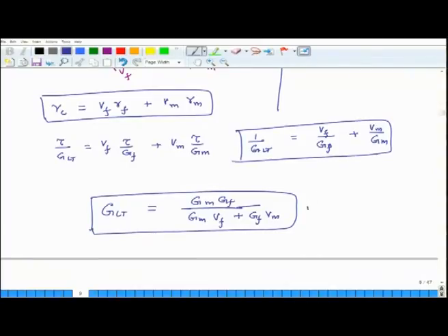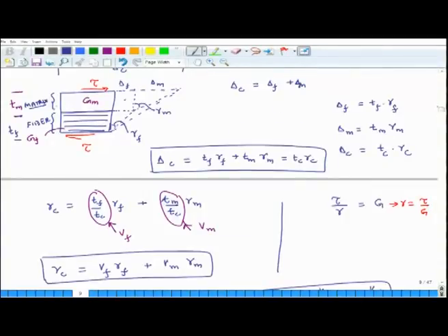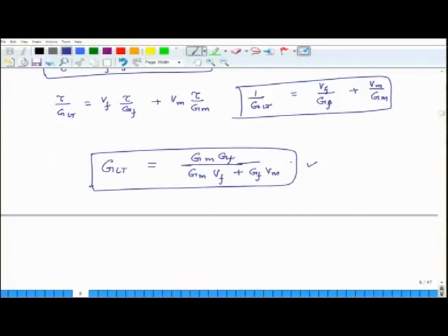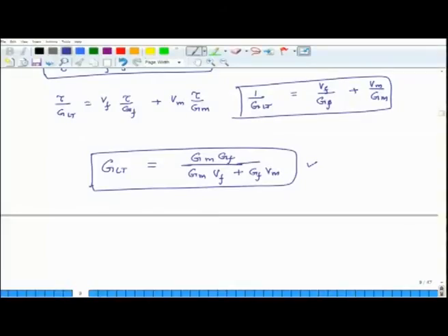So, using the model which I had explained earlier, I have separated the fiber and matrix and made a lot of simplifying assumptions, and using this approach I have developed the relation for shear modulus GLT for the composite. Now, when I calculate the value of GLT from this formula and compare it with experimental values, just as in the case of transverse modulus, there was disagreement between experimental data and the model.